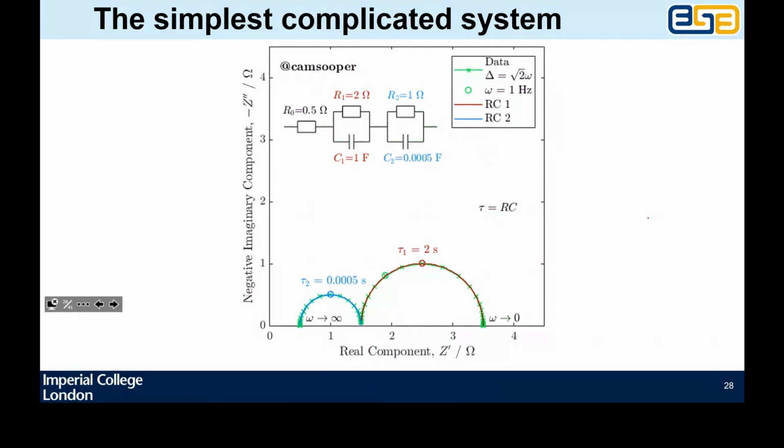They become fully blocked. So at a low enough frequency, both of these capacitors, irrespective of their value of C, at a super ultra low frequency, they're just both full. They're really extended springs that are pushing back really hard, which means this circuit becomes a resistor, followed by a resistor, followed by a resistor.